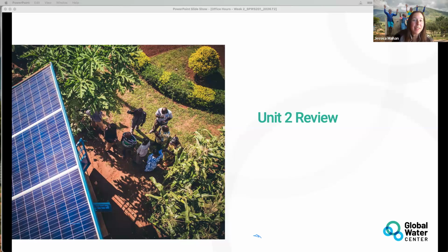And so the challenging part, right, is determining, okay, what are those steps going to be? You have to have an idea of what you think the borehole is going to be able to produce before you go into that step test or that pump test. Mainly because you need a pump that can hopefully work, right? You don't want to use a pump for your pump test that's going to pump way too much water or not enough water because you want to find that true maximum and you don't want to over pump right off the start, right? So you have to be able to estimate what your borehole can do before you've done a pump test. That's the challenge, right? So yes, there's a couple ways we could do that.